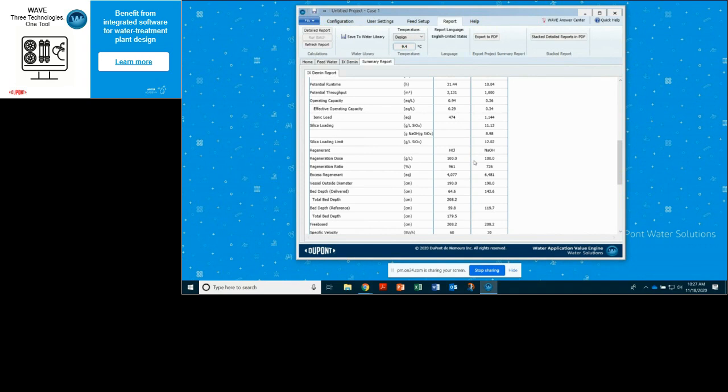So our traditional Marathon C, which is now our Amberlite HPR 1200, is dark and can be used in a mixed bed, which is nice if you already have a 2-bed demin system where you're using that as the primary cation, and so you can just streamline and have one. But either one can be used, the 1300 or the 1200. I just wanted to answer that question.